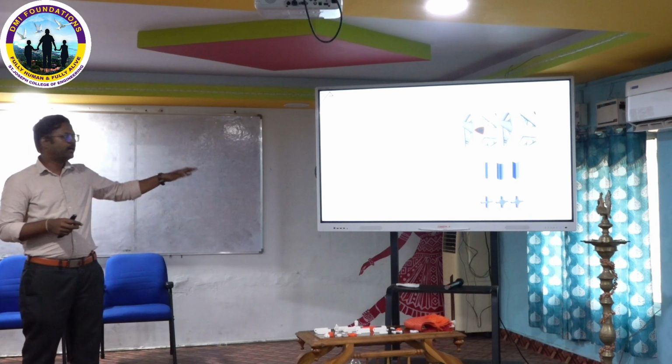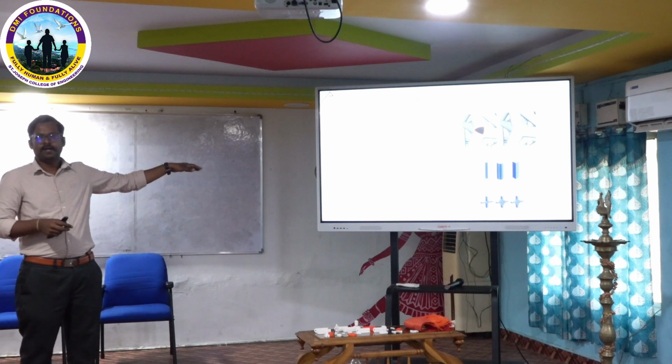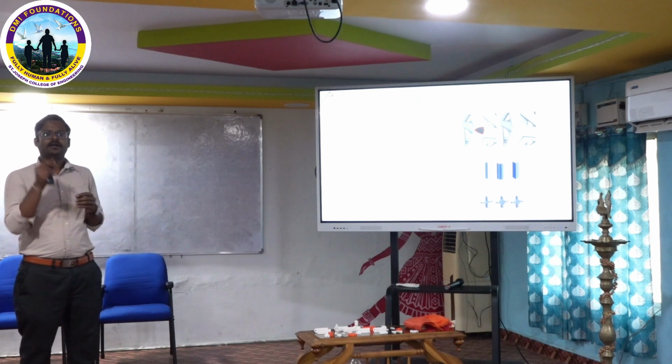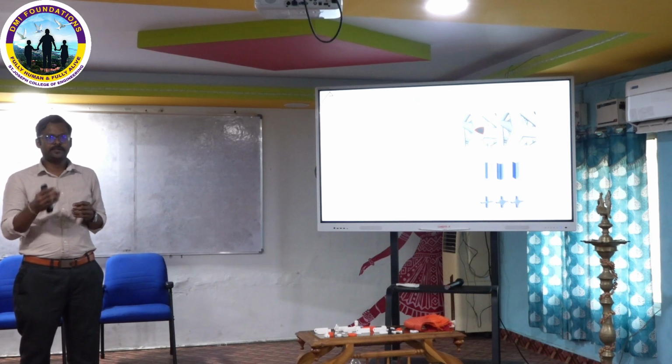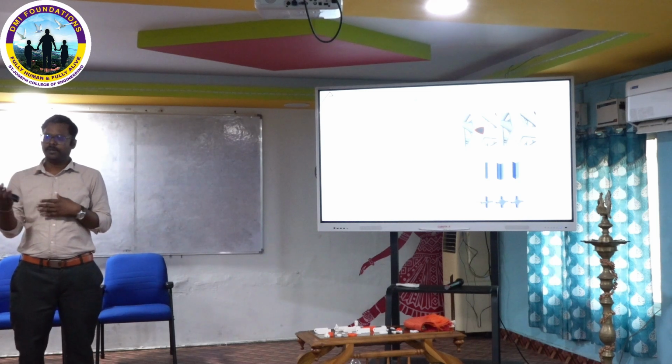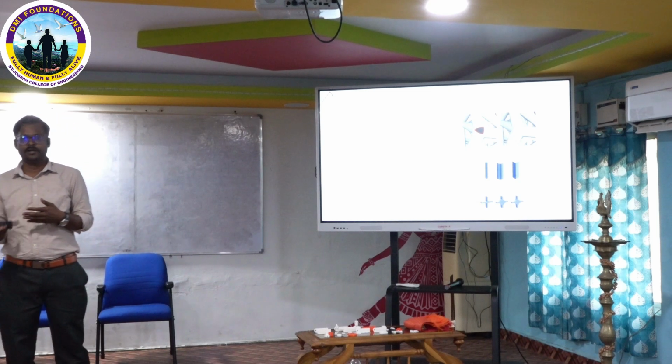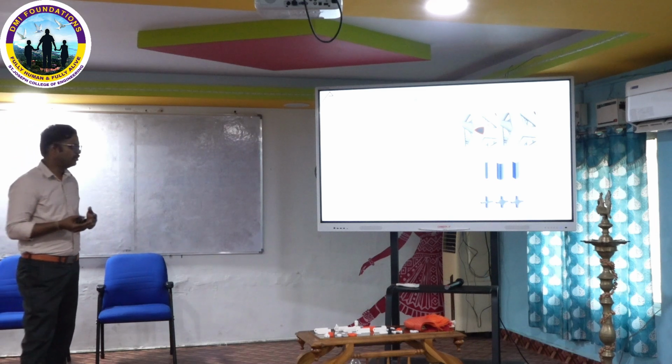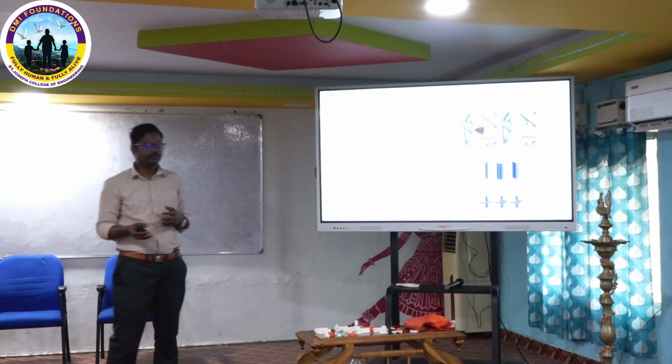So based on that, you have to get that. But what happens now? If you go with the maximum size of mesh, sometimes an error will happen. Then the FEA part is interrupted. So these are the things we need to do.